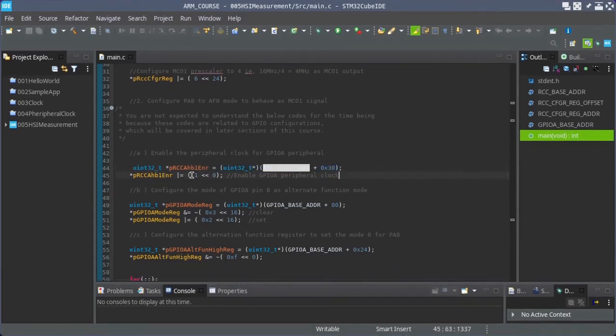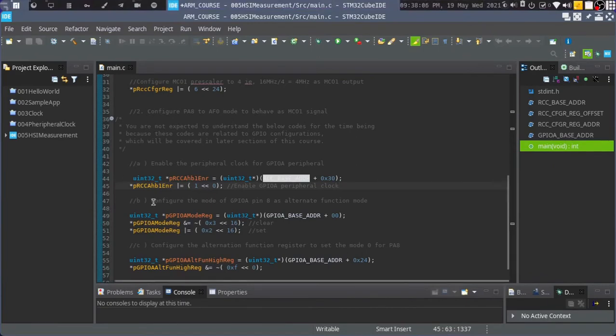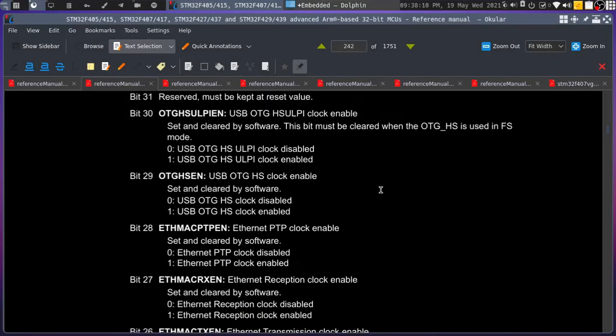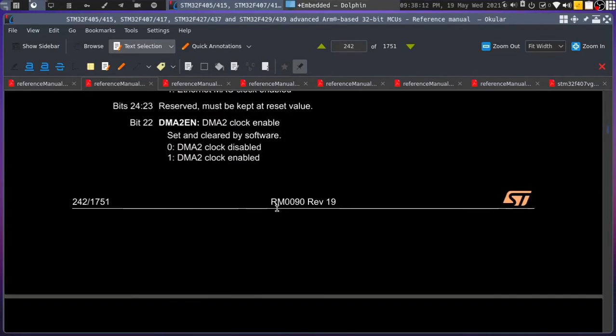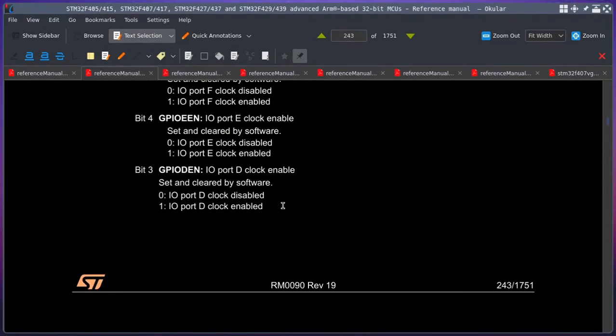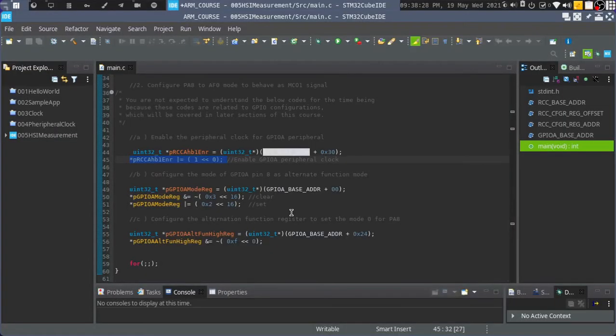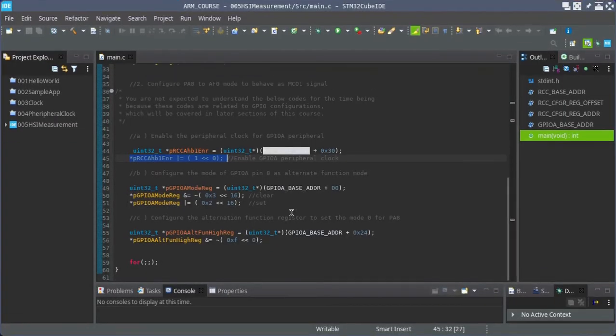So it's basically which value I need to write. From the code itself it is clear that I need to set the bit. Let us confirm that by looking at the datasheet. It is the 0th bit. If you go below on the datasheet page, you can see that to enable GPIOA, we need to set 1 to that bit. Only then can we start configuring the registers related to GPIOA.